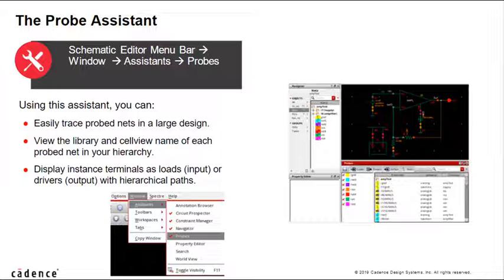The input, output and input-output pins connected to the probed net have been classified as loads, drivers and in-out respectively. So you can see this in the display, making it easier to understand a large schematic design.